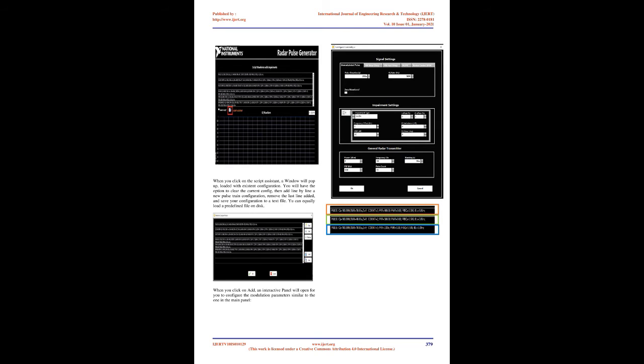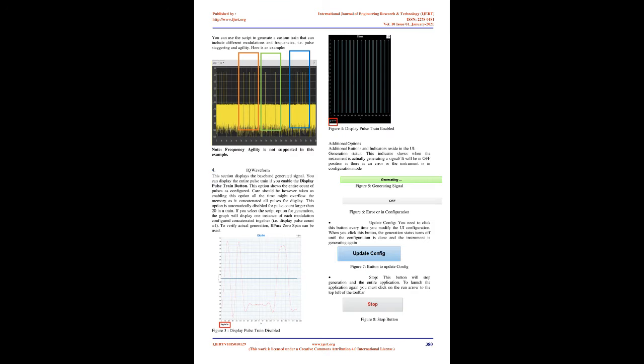5. Barker-coded BPSK, phase-coded waveforms differ from FM waveforms in that the long pulse is subdivided into a number of shorter sub-pulses. Generally, each sub-pulse corresponds with a range bin. The sub-pulses are of equal time duration, each is transmitted with a particular phase. The phase of each sub-pulse is selected in accordance with a phase code. The most widely used type of phase coding is binary coding.